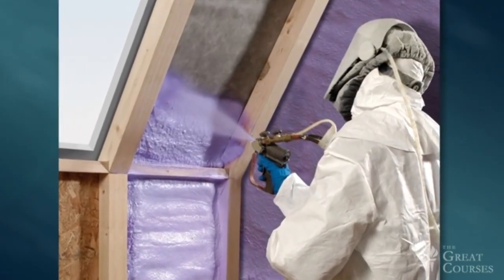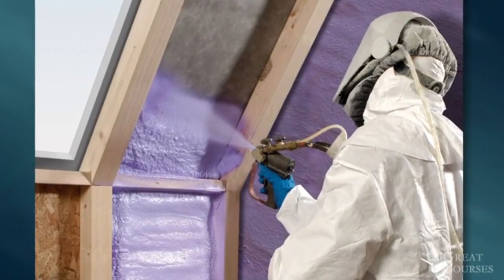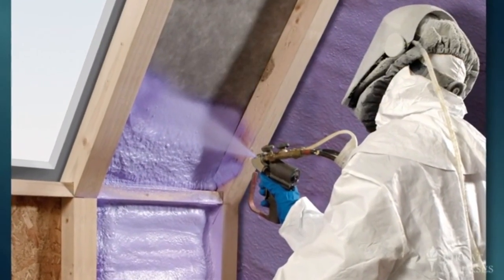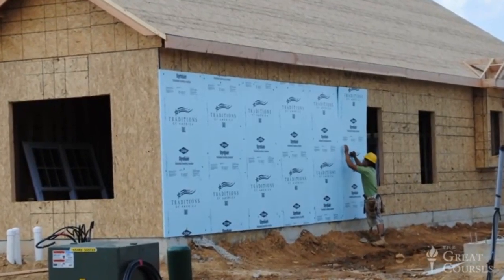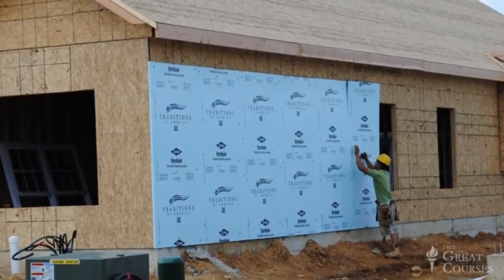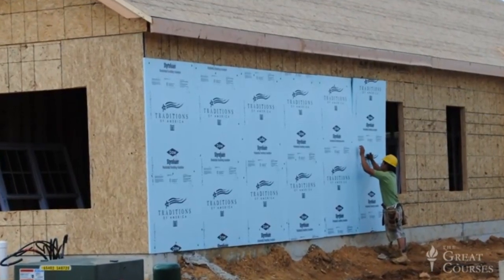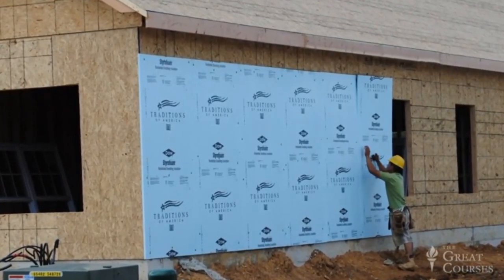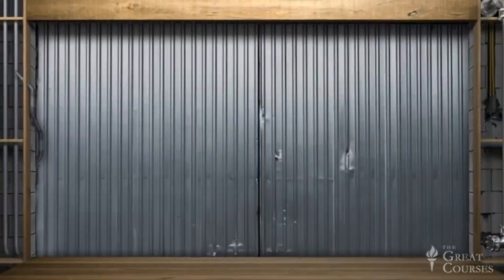Sprayed and foamed in place insulations are even better at filling tight spaces, and many of them have impressive R values as well. And finally, rigid board insulation is typically applied on the outside of the wall, as you see here, so there's no possibility of interference with internal utilities. The bottom line: it no longer makes sense to simply assume that fiberglass batting is the right answer for all of our home insulation needs simply because we've always used it before.